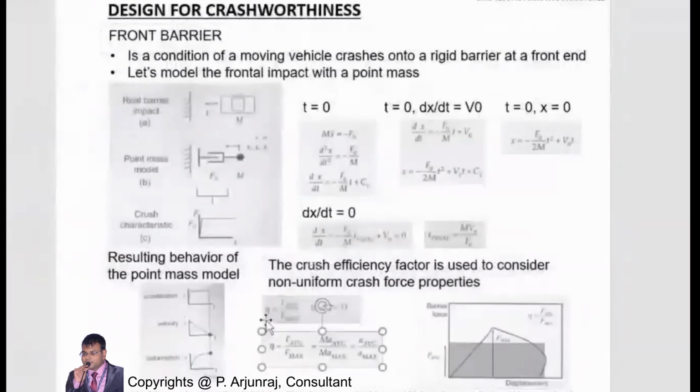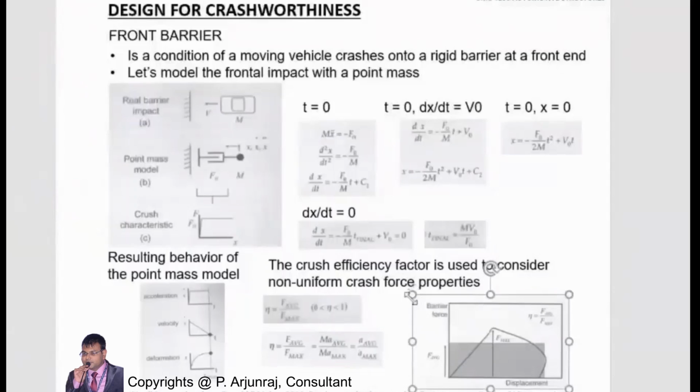The efficiency is nothing but the average force to that of the maximum force which is going to act, and this crash efficiency factor should lie between 0 and 1. And this can also be defined as the ratio of average acceleration to that of the maximum acceleration.